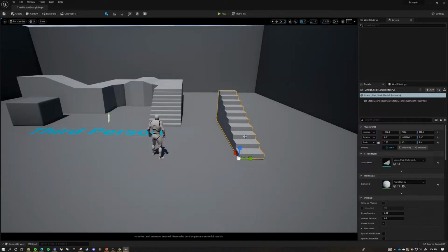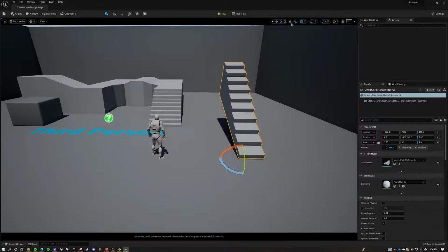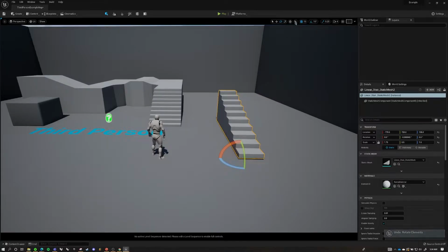The button to the right of those other 4 determines if the gumball is based on the local geometry or the world plane. The local gumball will match the orientation of the object, while the world gumball will always face the same way after editing an object. Next to that are surface snap settings, like OSnap settings.